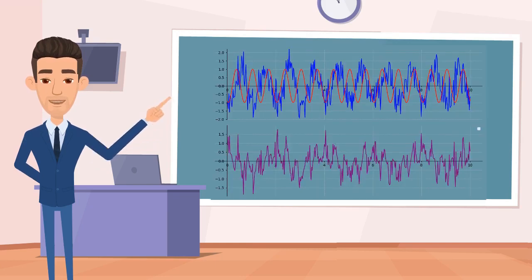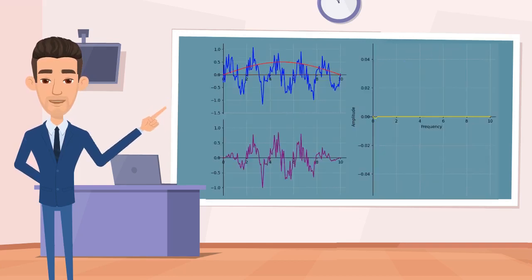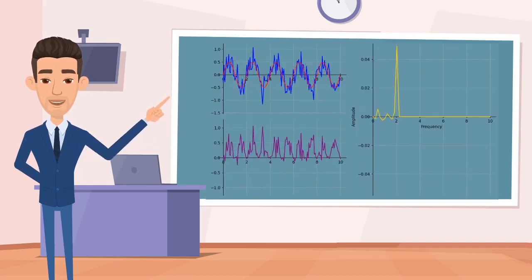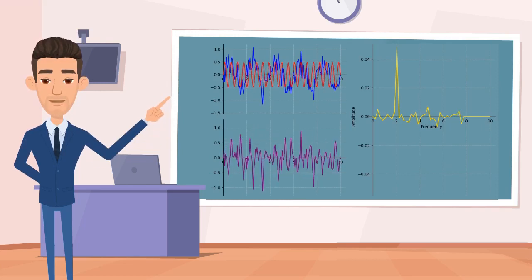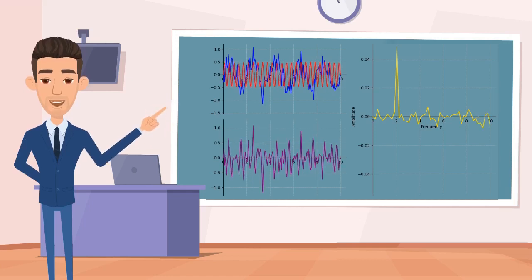To find a specific value, we multiply the original signal by a sine or cosine wave, the same frequency we're interested in. Then we sum up these products over the signal's entire period. In other words, we find the total area of the product wave.